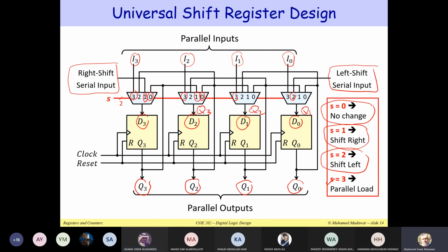It's the most commonly used. The D flip-flop today is the most commonly used, and this is my focus. But later when I talk about counters, I'm going to show you another type of flip-flop, which is the T flip-flop. I'm going to show you how we can implement counters using the D type as well as the T type, because the T type can simplify the implementation of counters.